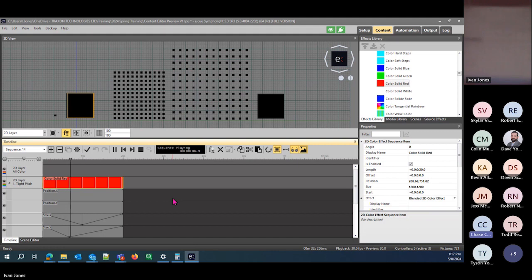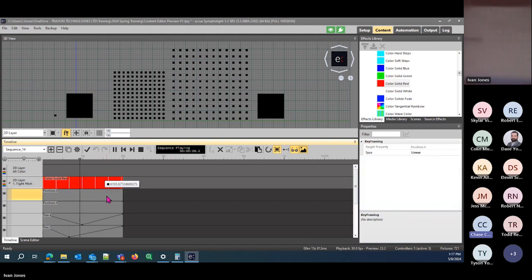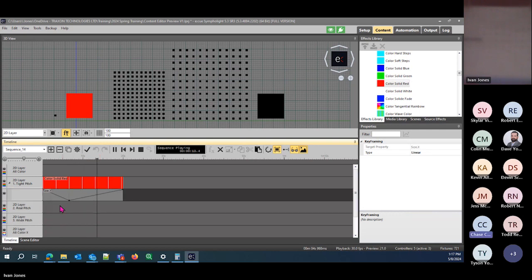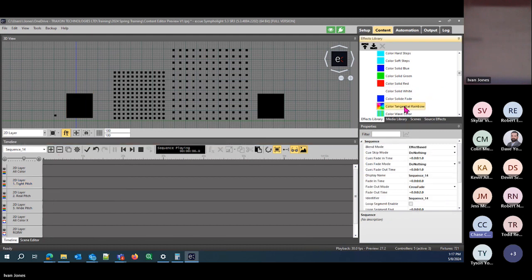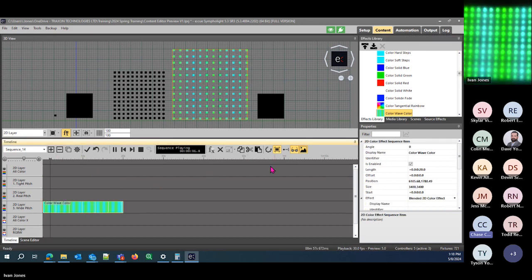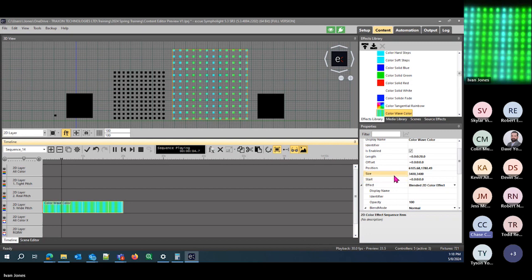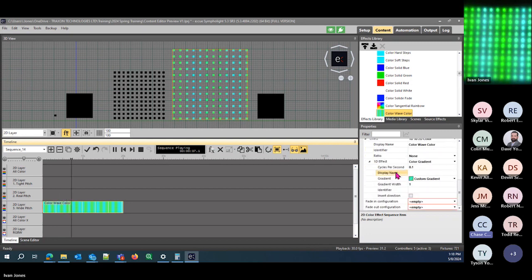And another good thing to use, a cool thing we can use keyframing for, is to create a number or to change a number over time. So we can almost use a dummy cue list, or rather a dummy sequence and a dummy effect that's in a group that doesn't pertain to anything or that's moved out of the standard area, and use that keyframing information and that change of value to create moving numbers into the automation editor. So keyframing's got a lot of cool uses and quite a bit of power in both content creation and also automation.